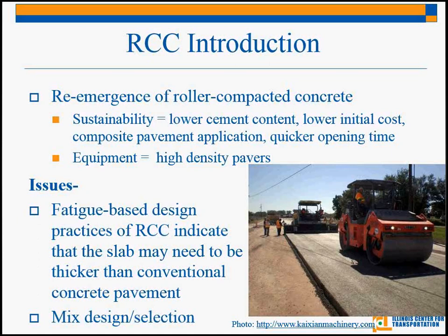So we're lowering costs and lowering emissions. And because it's such a dry mix, you can open it to traffic more quickly as a pavement, because you don't have to have the long hydration time.